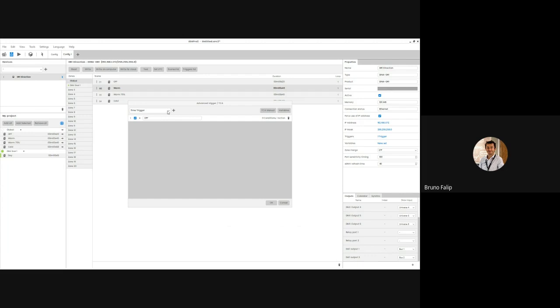And this is also very useful if you, for example, want to assign a DMX input channel to a dimmer of your scene. So you can also create a variable which is DMX input, and you can link it to the dimmer. So you have any standard DMX text to adjust the dimmer intensity or the speed or whatever of your lighting scenes.